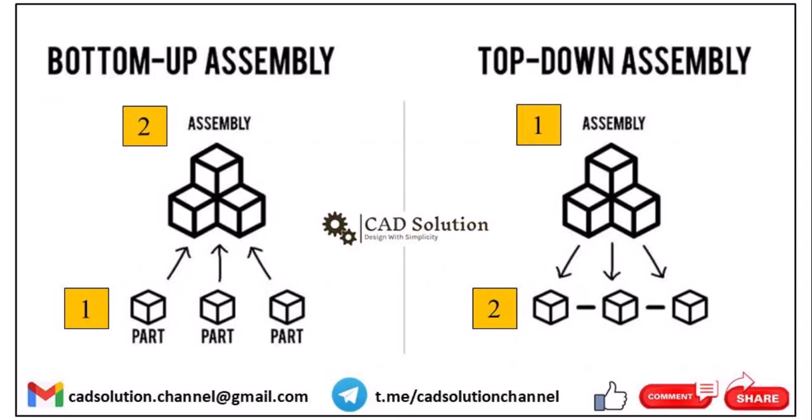First of all, let's understand what is bottom-up assembly and top-down assembly. In bottom-up assembly, parts are separately created, and in assembly workbench, parts are called one by one for the assembly. Whereas in top-down assembly, parts are created in the assembly workbench itself using the reference of the mating parts. This is the basic difference between bottom-up assembly and top-down assembly.